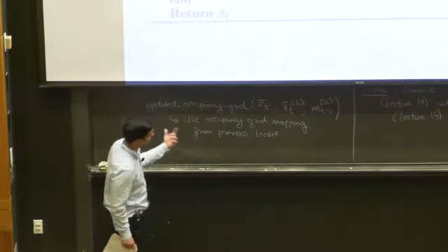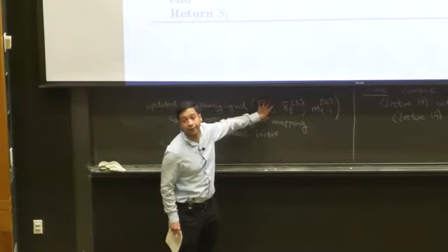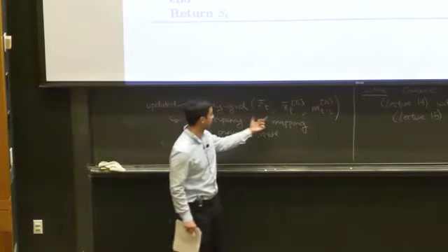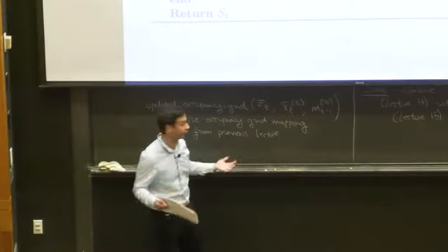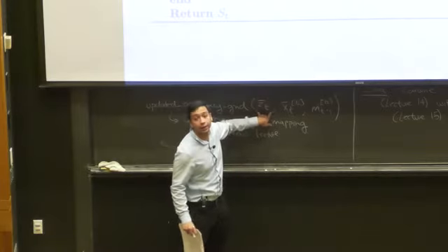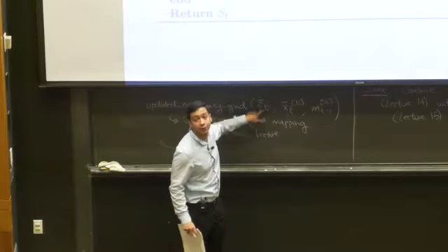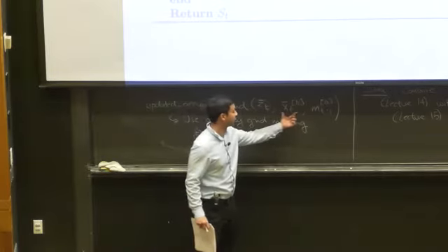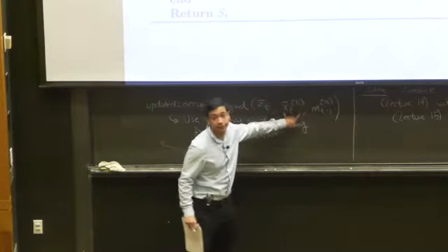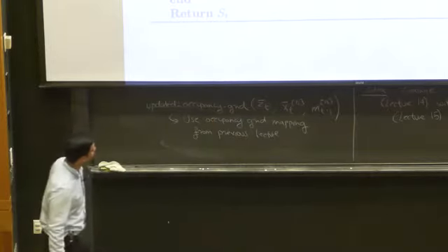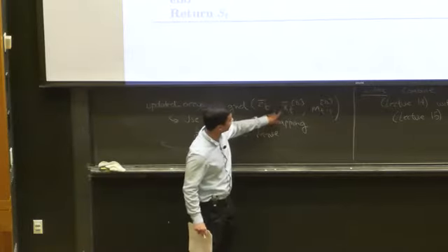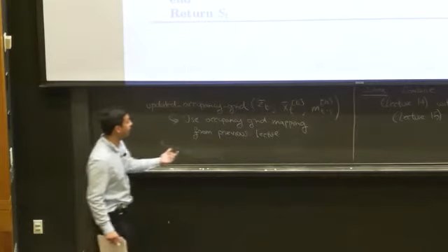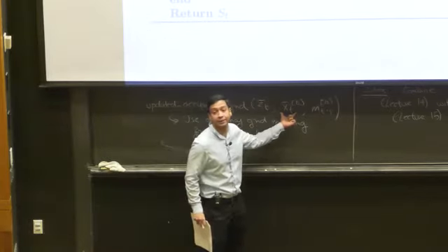Then we can use the occupancy grid mapping update of the beliefs that we described in the previous lecture, where you take the prior over maps and incorporate the sensor measurement you just received at time step t, which could be noisy, and then incorporate this location x_t. So we're applying the occupancy grid map technique, but assuming that the location is correct.